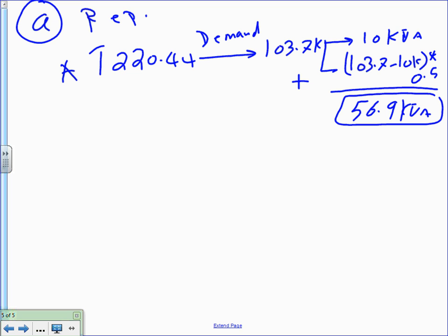Now, do me a favor. I want you to highlight this and put 2 stars next to it. This is the demand for all your receptacle load. Everything receptacle, that's your demand for it, right? No, I'm sorry, we still need to compare it. The last step that we do is choose the largest.